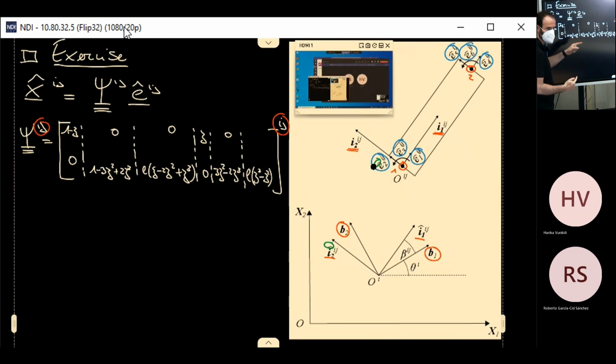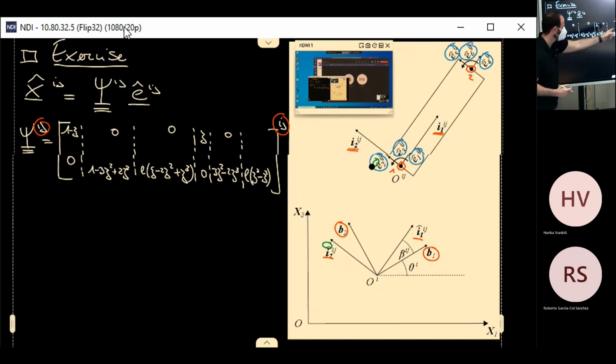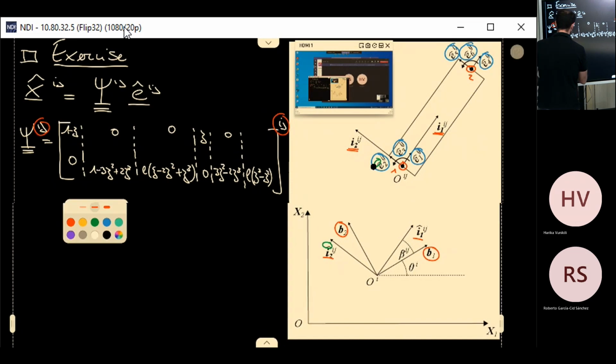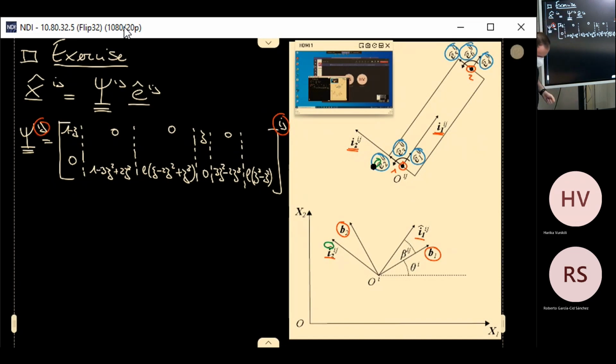And also xc is the normalized distance with respect to the length of the element j. Instead of putting j all over the various quantities, I just put it here on the matrix. But this is the meaning. But as you can see, it's always the typical shape function, which is always again the same because it depends on the physics, and we always made use of the typical Euler beam 1D model.